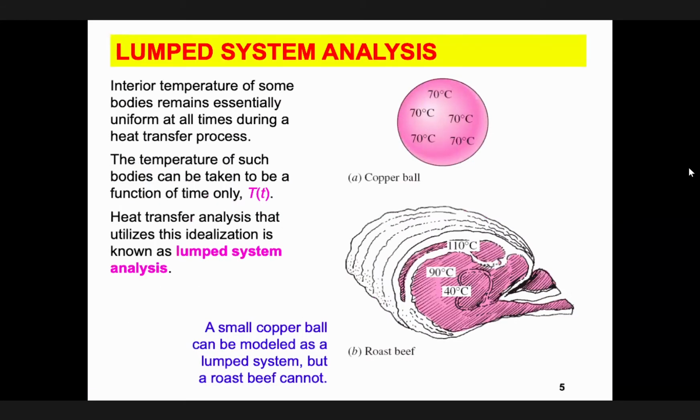For example, the first assumption that we mentioned, okay? If I look at this, it is made of copper, so I can assume this because of its high conductivity. I can assume the temperature everywhere inside the sphere, not only on the surface but inside also, is 70 degrees, because it has high conductivity. As heat reaches the surface, it can penetrate fast inside. If I use an analogy, convective heat transfer comes here and then goes here. It's like coming to downtown Montreal with very heavy traffic; when you get to the highway, you can go fast.